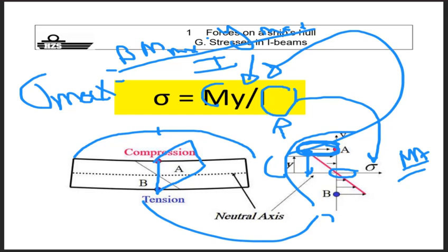So if this is in order, then you can say that your beam is fine and will not fail. But as soon as that stress level is higher than your yield stress or the restriction given by naval architects, or which naval architects use as a reference, usually it will be your yield point taking into account a safety margin. Neglecting now a bit the safety margin, just taking as a reference your yield point, as long as the maximum stress levels that you encounter on board are below the yield point, your structure is fine.